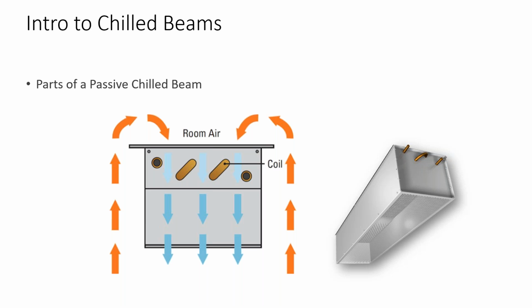And it works well with not only mixing with the various other active chill beams in the space, but even if you have a stratified air system with displacement in-wall diffusers or underfloor floor diffusers, you can still use this. And in fact, you get a bit of boost in capacity when you're stratifying. You've got warmer than set point temperature up above that ceiling space. So you've got 80, 85 degrees air across that coil, and you're cooling quite effectively in this manner.